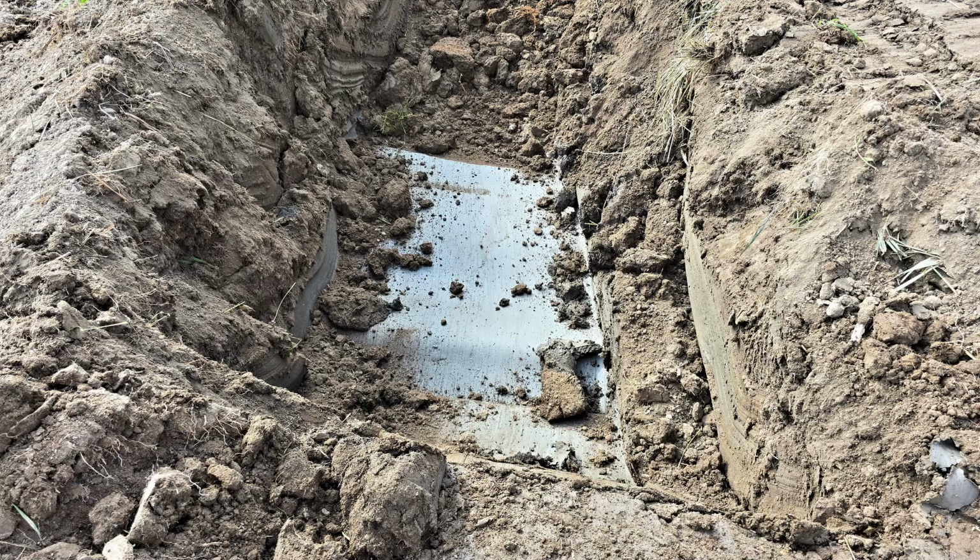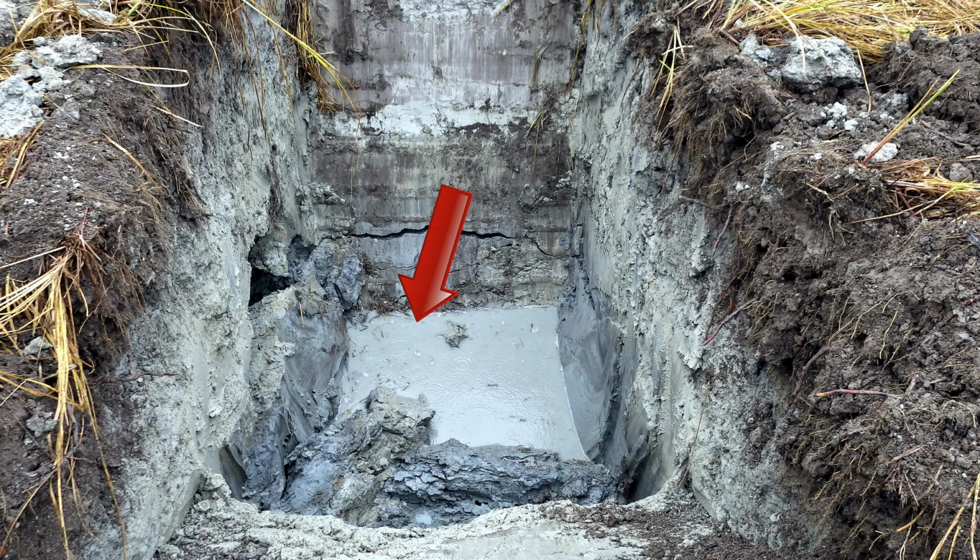The groundwater dam being built for this wetland is going to be based on gray-colored soil, which is a thick layer of soil that is very high in clay. The brown-colored soil near the surface is silt loam, and this soil is permeable. You can see where water is pooling in the bottom of this hole. This is a good sign that the clay layer is thick enough and dense enough to serve as an impermeable foundation for the groundwater dam.